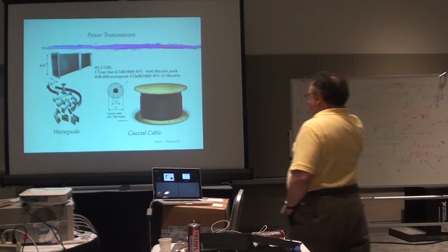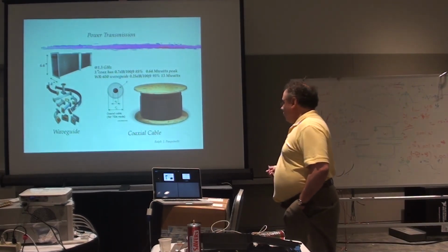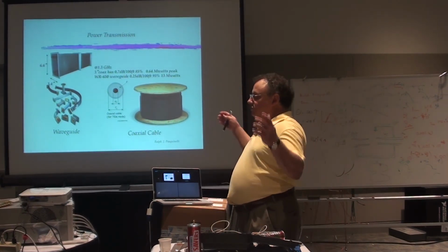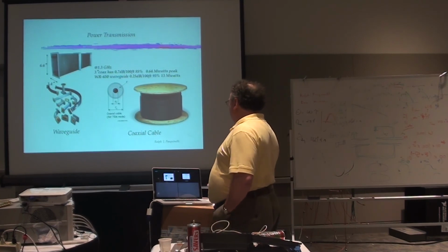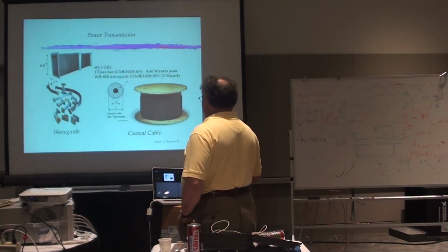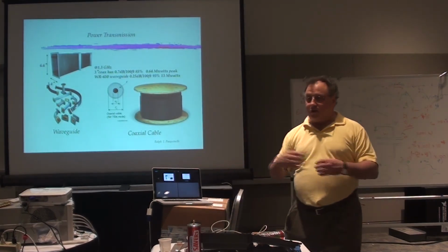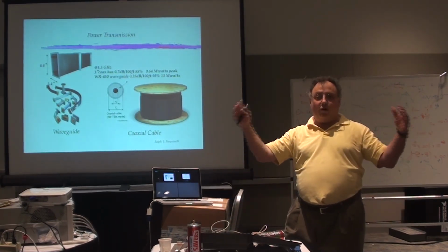If the power level is not high, certainly coax is much easier to work with than waveguide, and you don't have to put hundreds of bolts every few feet in it. But it's a question you need to worry about. Also, coax is TEM, and is very broadband. So for all our stochastic cooling stuff, we were trying to put 1 octave of signal in.